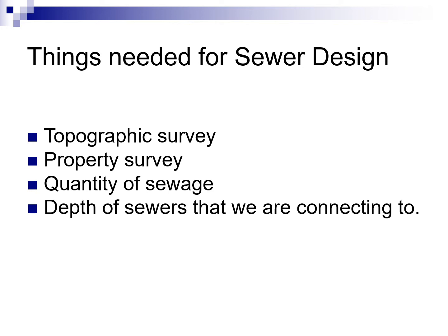Then we also need to know the quantity of sewage. The pipes have to be sized to carry the appropriate quantity away from the customers and to our sewage treatment plant. Then we also need to know the depth of the sewers that we are connecting to. That becomes important for a number of reasons, such as if you want to provide basement sewer service.